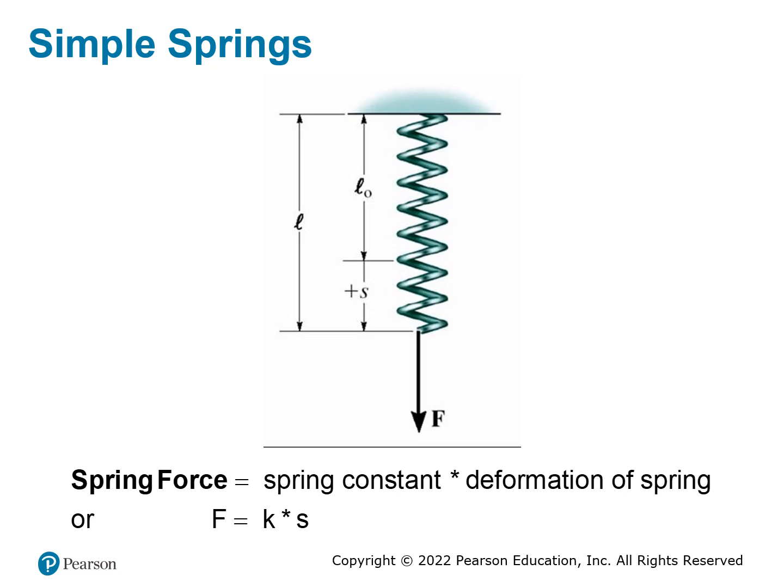One is how strong the spring is, which we categorize by what we call the spring constant, and we use K to represent the spring constant. So the spring constant represents how hard or how soft the spring is. If you can easily extend the spring, that means the spring constant is going to be small. If it's harder, then the number will be larger.